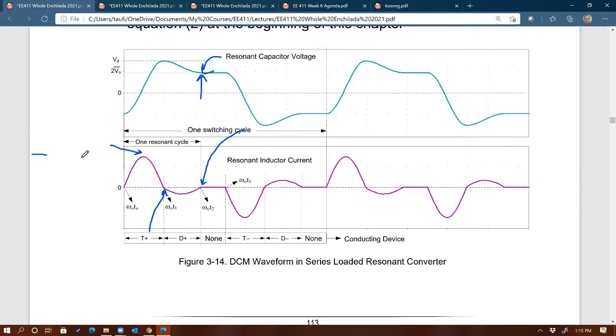So let's say the diode is conducting current, let's say this is diode current. And then when the diode is conducting and we want it to stop immediately, this is the 0, then this steep change, that's when you need a fast diode.